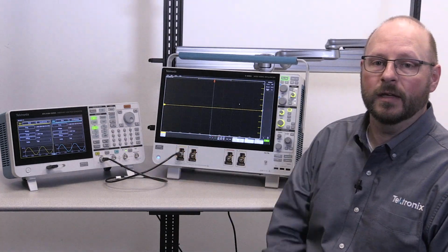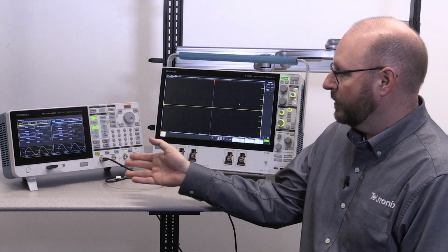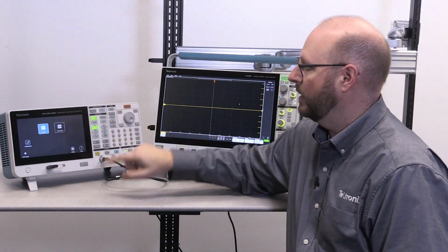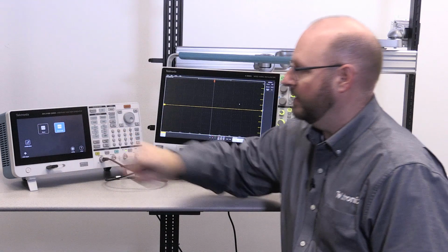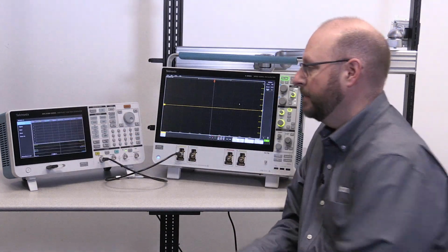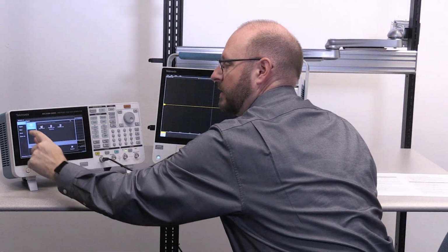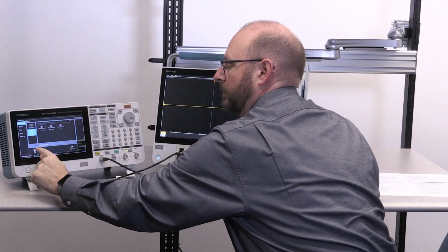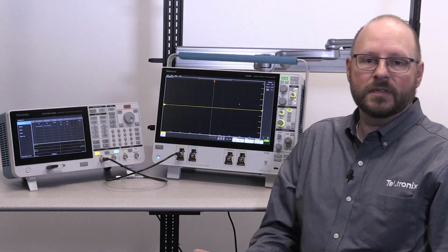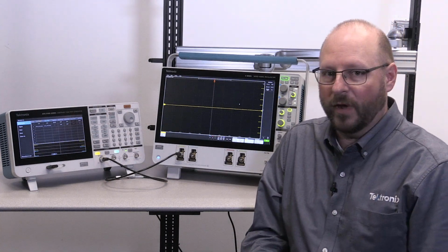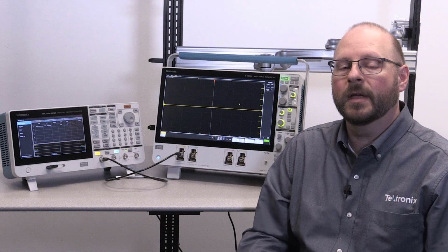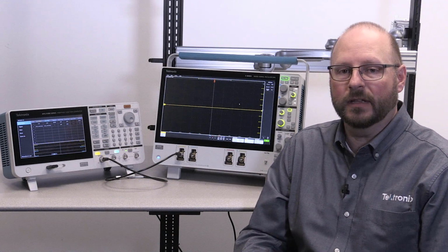into channel 1's input on the oscilloscope. For the demonstration, I'm going to use a saved sequence file, and I'm going to open up the advanced application on the AFG and recall that sequence from the attached USB drive. Now this sequence is designed to output a normal sine wave 50,000 times and then one with a few signal anomalies one time, and it repeats that sequence indefinitely.